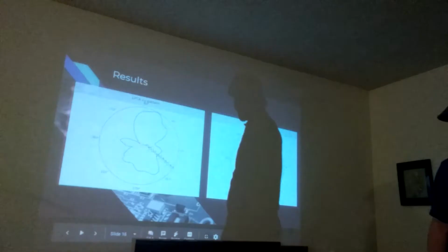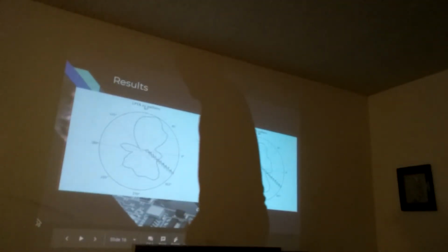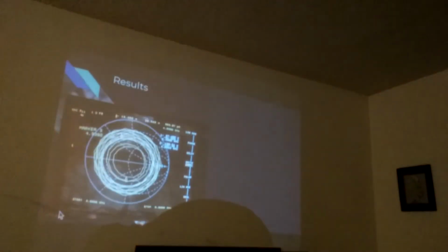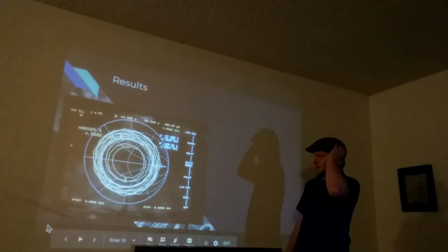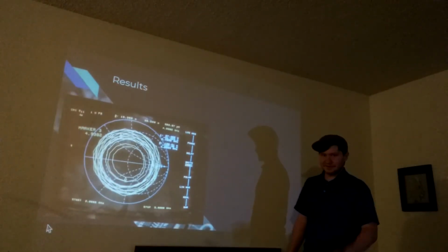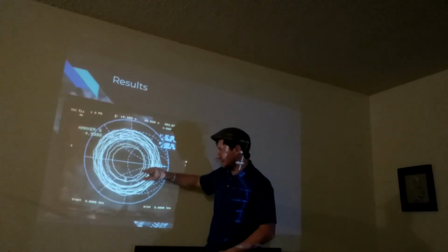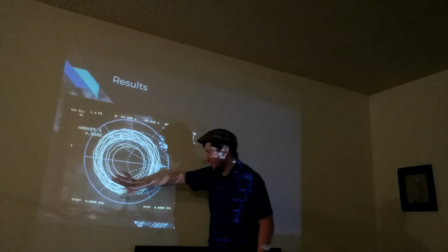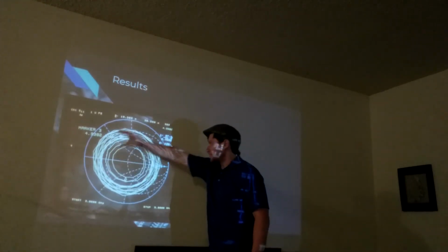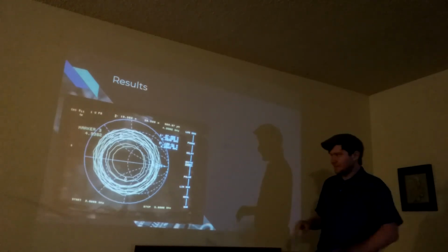So, whoops, going back a slide. I plugged the antenna into the spectrum analyzer. I noticed that unlike other antennas that I tested, instead of getting a loop in here or a couple loops in there, it was kind of like this nice circular band around one VSWR circle.